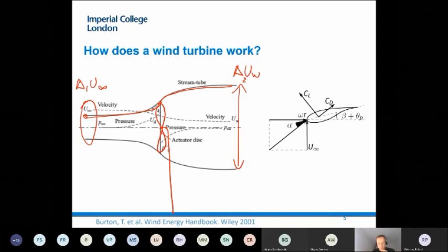That extraction of energy goes into a converter. The converter goes into a generator. Generators are typically installed on the nacelle. And for very large wind turbines, getting an idea of size is important. So a very large wind turbine typically has a tip to bottom height of about 150 to 200 meters right now, the largest ones, very, very large. Rotors are approaching about 100 meters in terms of dimensions. And nacelles, which is where you put the gearbox and most of the energy transformation systems, are of the order of several hundred tons. Okay, these are massive constructions.